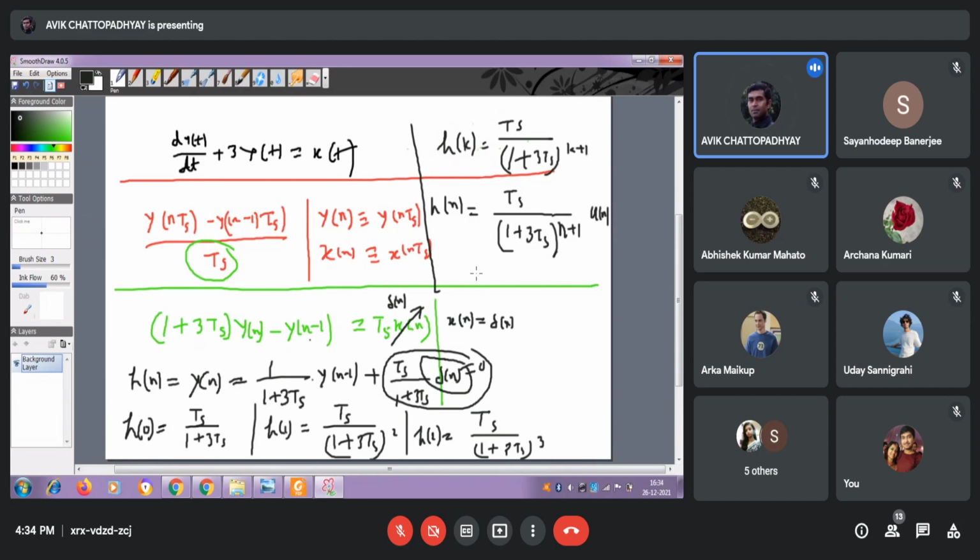That is the impulse response of that discretized version, which is written in green color, of that differential equation. This is a signal after all, h[n]. Now, if I know this signal, or the form of this, then given any input, it doesn't matter, I will simply do the convolution and find out the output y[n], which means actually y(t). So that is possible.